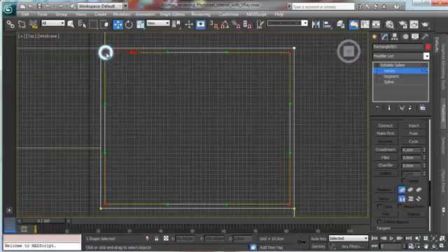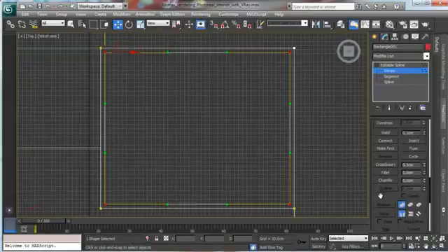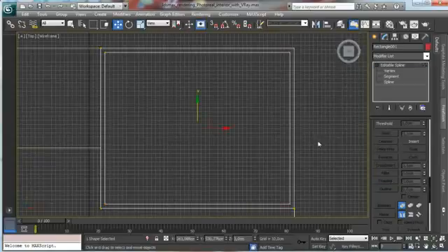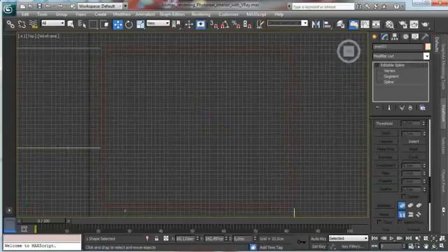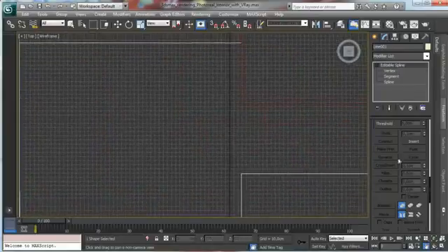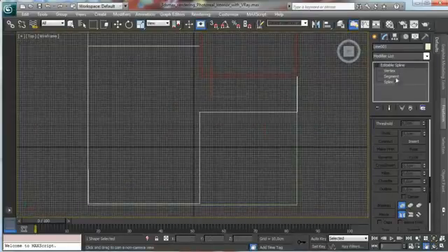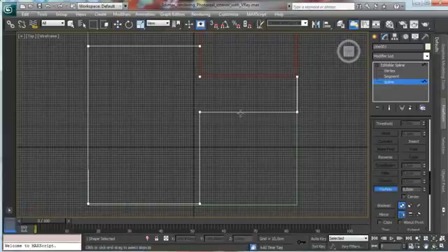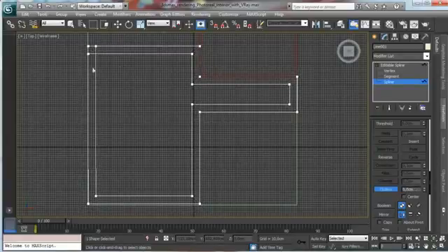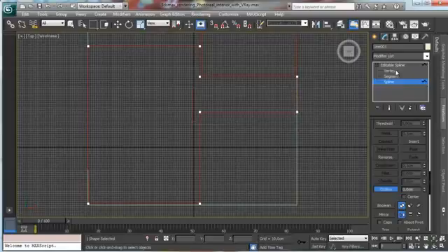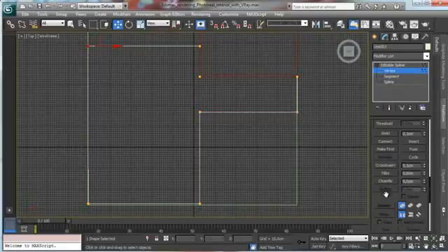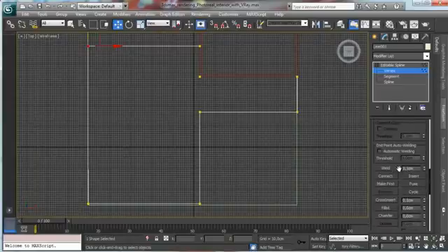Sorry, I have a problem seeing the quad button, but I'd like to do the fillet, so in the meantime let's do the fillet, 0.5. Okay, done. Then we need to do the same for the other one, so there let's do spline and outline, and we can do it. Okay, there's a problem there with the vertices, so let's check those vertices, and let's say weld. Okay, now it should work.